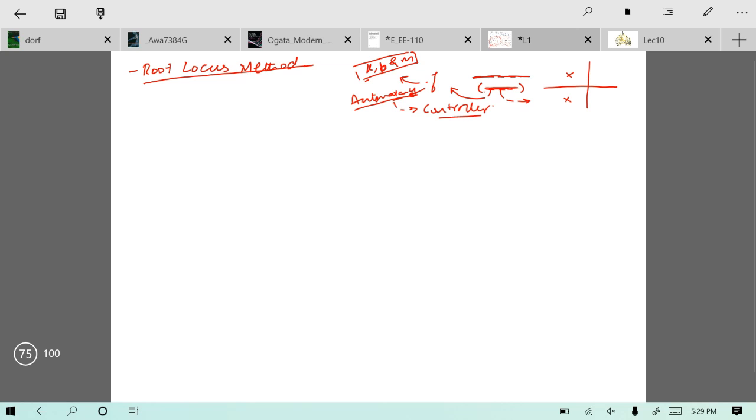For example, if you want your system to be non-sensitive towards disturbances, and those disturbances tend to change your internal parameters such that zeta changes. In your mass spring system, with time the frictional constant may change, and with time the spring constant may change, so zeta will change, the characteristic equation will change, and the location of the poles will change. A new system may have poles at one location, and when the system gets old, the poles may move somewhat to another location.